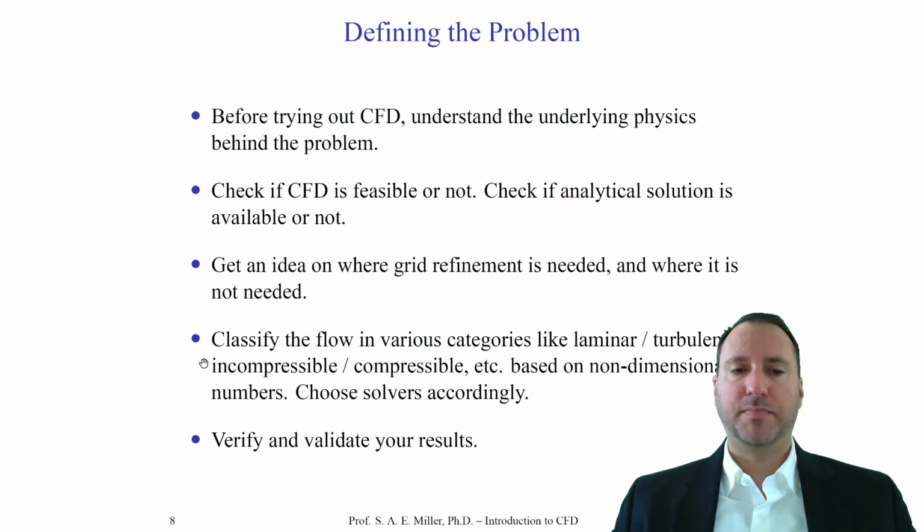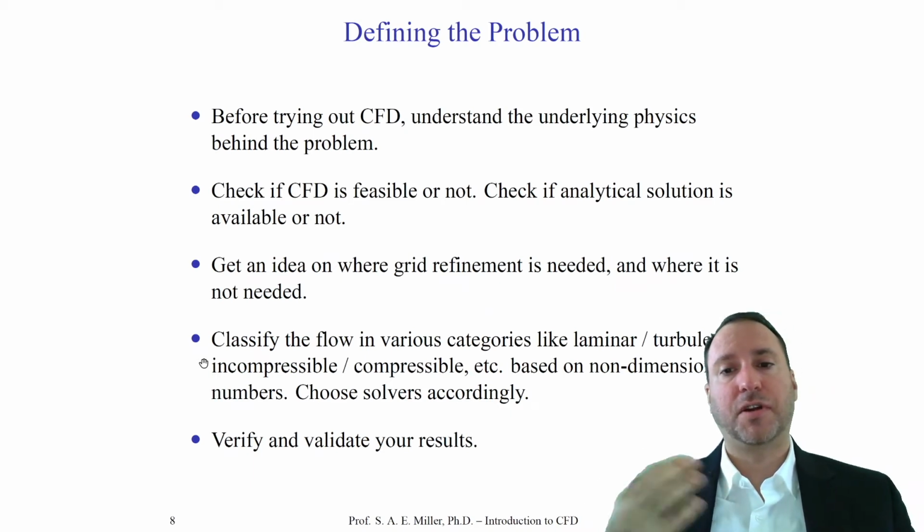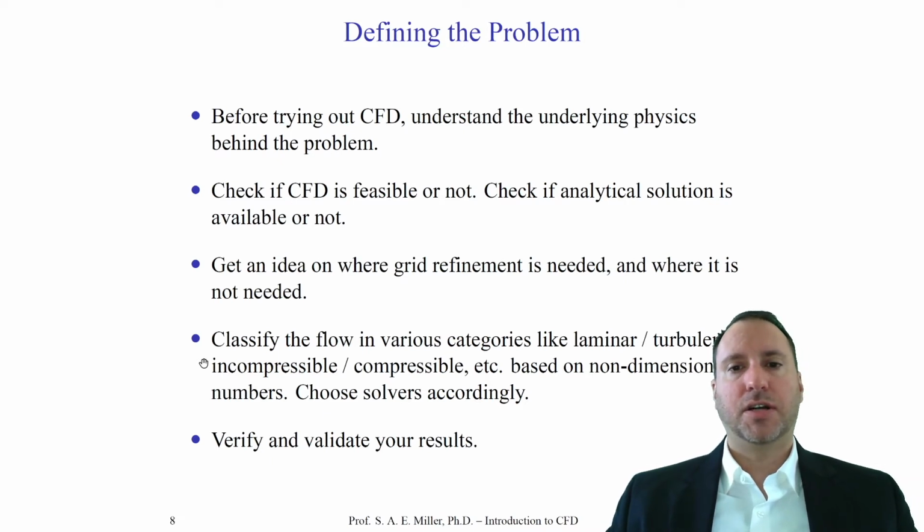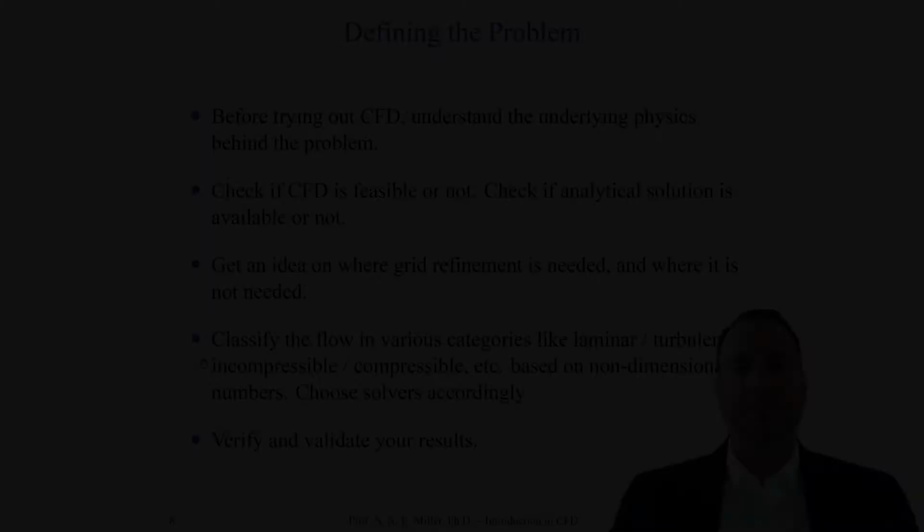You might run it against benchmark cases that you know solutions to, like analytical solutions, or compare them with some baseline experiments. And that is done on a regular basis with CFD solvers and development groups, and is certainly done in production and industry where people want to make sure that they're running the solvers correctly, because they're obviously very large and complex systems, as you're starting to see in the class.